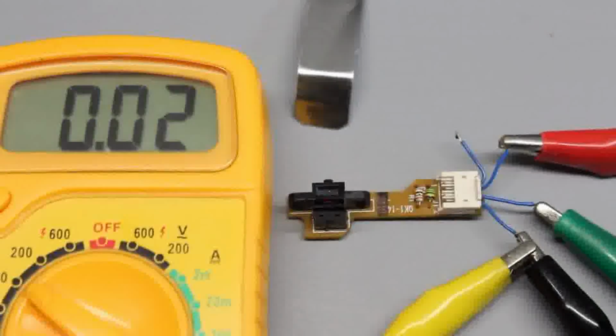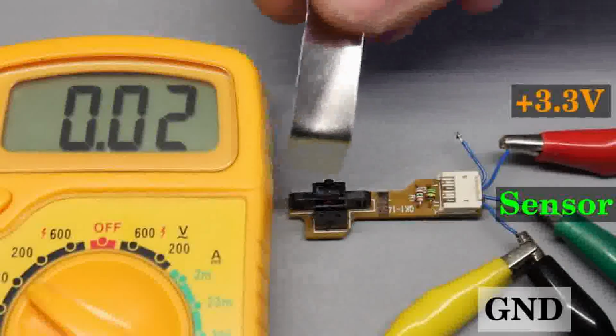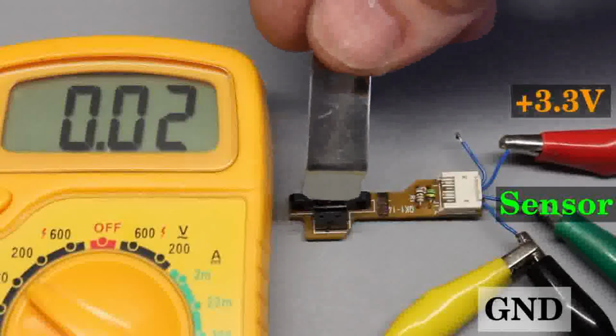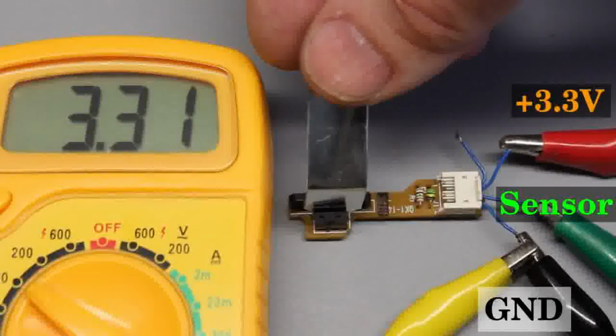The sensor units are usually operated at 5V, but you should try 3.3V first to do it the safe way. As you can see, it works perfectly.